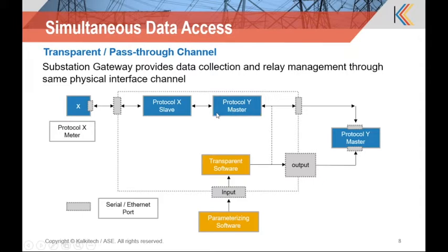Another is the cycle stealing method, in which the master protocol communicates and sends a packet, and in between, when there is data from the parameterization tool, it is sent through the same channel over the protocol port, and the reply is sent to the transparent channel too. So one message from the protocol master and the reply to that, and another message from the parameterization tool and the reply to that. Like that, it functions in the cycle stealing method.